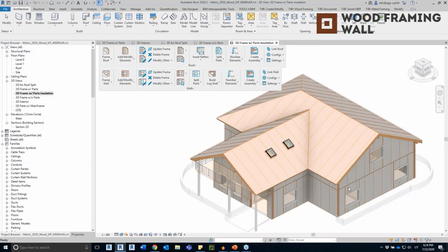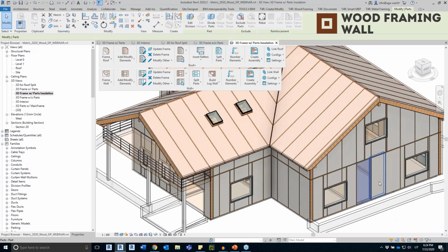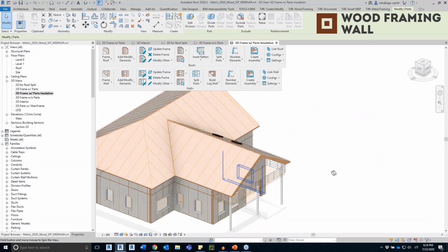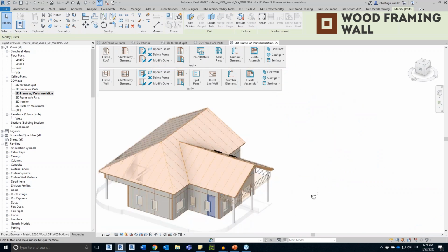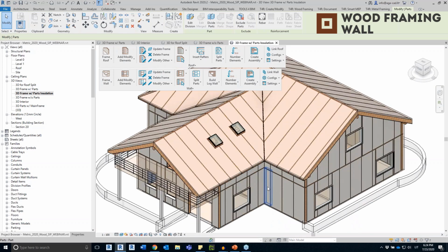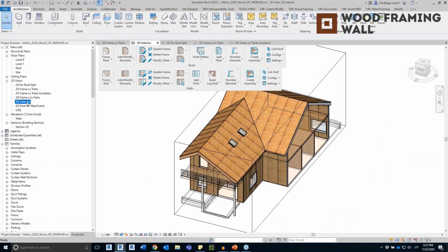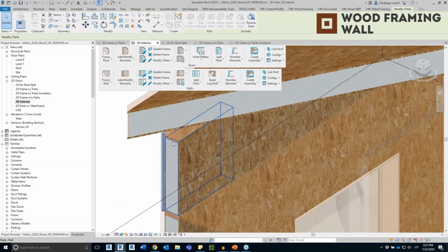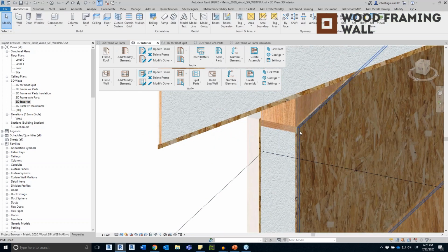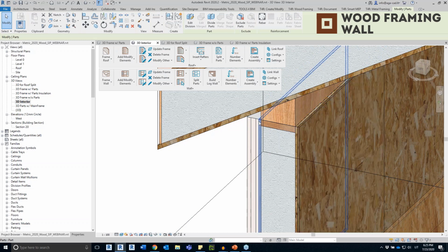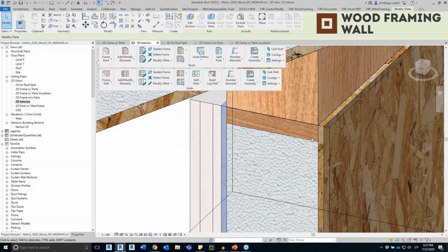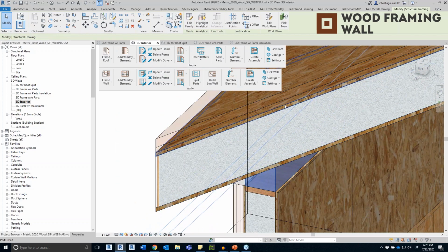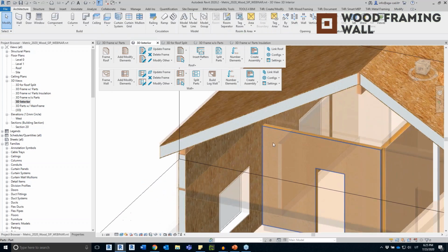So I have the SIP panels created for the whole building. And again, let's take a look at the view with insulation parts only. You can see them between the studs that were previously aligned. Yeah, like this. And now also I will open another 3D view where you can see the parts cut. So yeah, these are the boards on each side. And this is the foam core, this is the wall stop plate, and on top of that I have a girder and the roof SIP panel. And also here I have an interior wall.